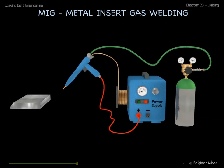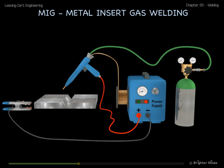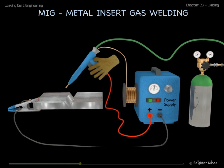The metals to be joined are placed or clamped together. The electrical circuit is completed by connecting the metals to the other side of the power supply using the earth clamp. The power is turned on. The gun issues the shielding gas over the weld area.